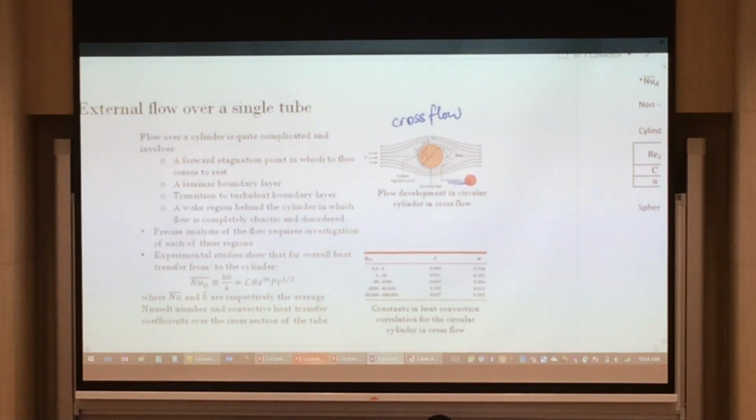The separation point is a point just like in your plate system, where you have laminar flow transiting into turbulent flow. So the separation point is also the point where it transits from laminar flow to turbulent flow. After the separation point, you will see everything over here is turbulent. And we call that turbulent region the wake of that cross flow. So the wake will just continue on in that way, and sometimes further down, the whole flow will get streamlined back again.